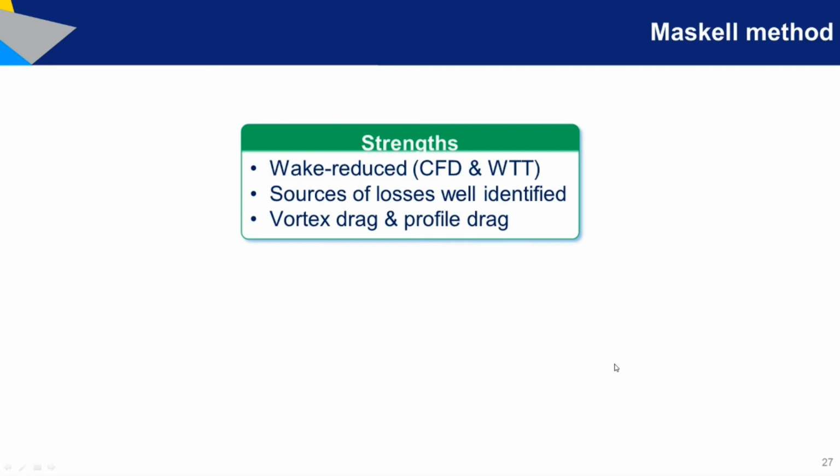So let's summarize all that. We'll start first with the strength of the Maskell method. The very good news here is that it is a wake-based approach, so we can use that either for CFD and wind tunnel testing methods. Both Maskell and Betz are available in Epsilon. You can compute drag and lift based on CFD and wind tunnel data.